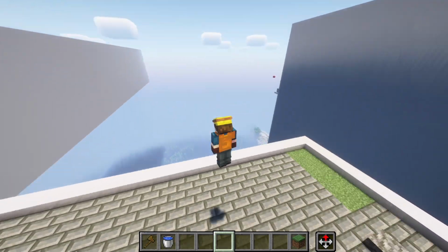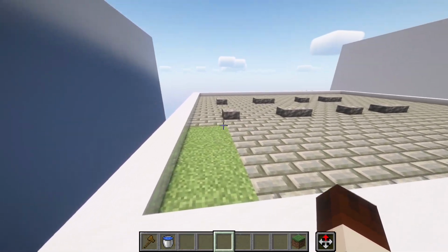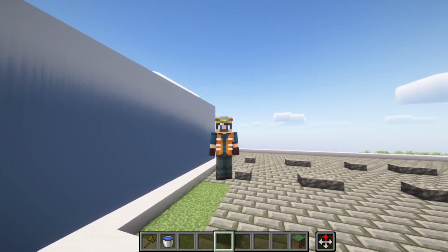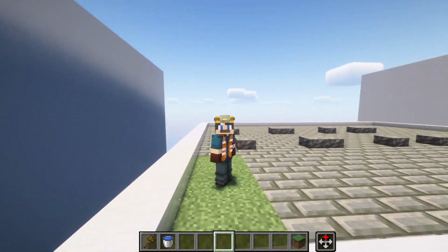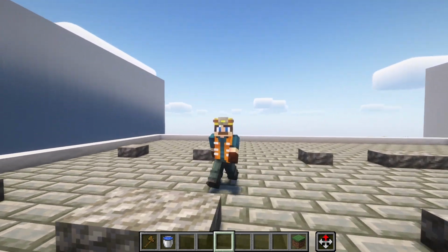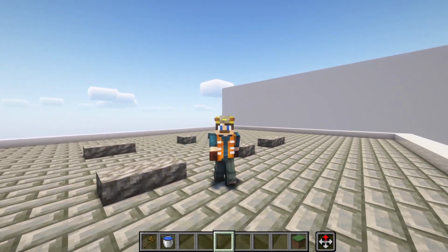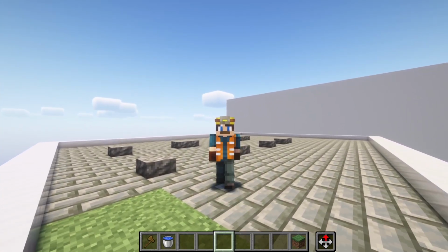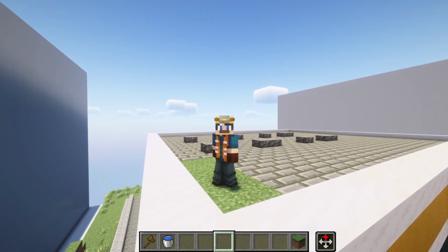And as previously mentioned in another episode, we went ahead and added what is a makeshift area for a green roof here. Now, you may or may not have seen what a green roof or a rain garden is, but for example, take this little green splotch here in the corner of our gas station roof. If we pretend that most of this is impermeable, once again, water cannot infiltrate this. This is some sort of barrier canvas for the roof of our gas station. All the water can make its way over to this area here, which is the green roof or green infrastructure.